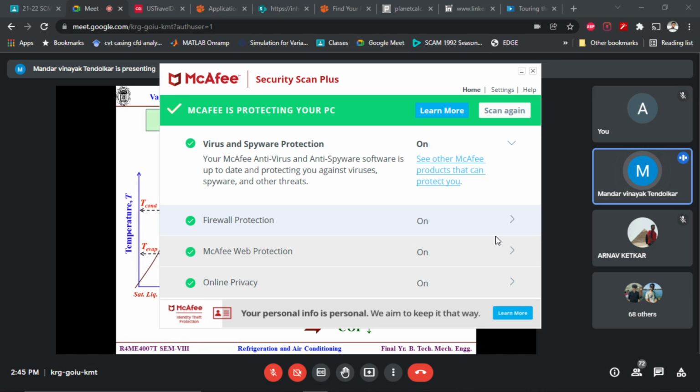It will never be the same as that of the Carnot cycle. Now the Q absorbed in the Carnot cycle minus Q absorbed in the VCC. So how much is that? The hatched part, correct? D4 4-CD. We have seen earlier, yes. The old part is this, the new part is this. So the hatched part is the balance. And that will give me H3 minus H4 dash, which is the same as H4 minus H4 dash, because H3 is the same as H4.